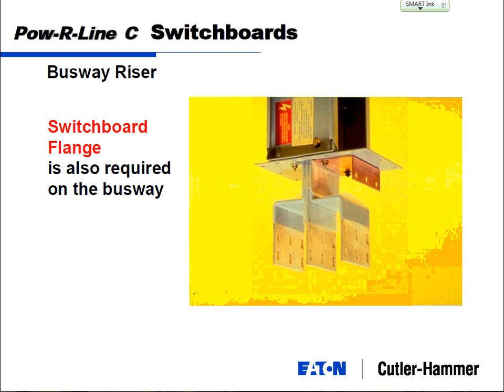So you could have 3,000 amps of busway that is this size. 3,000 amps of cable might be a bundle of stuff like this. So you can save a lot of size, and you can save a lot of install cost, because busway could be installed in a fraction of the time. The other reason folks use busway is, for example, on a high rise where you need to get power all the way up, maybe to the 20th floor. Think about what happens if you run cable from the basement to the 20th floor. What's the number one problem you're going to run into? Voltage drop.